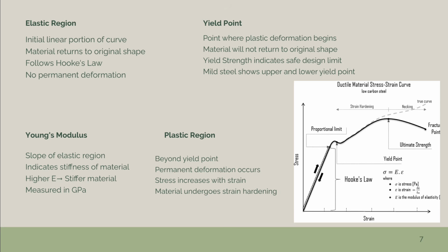The next stage is the strain hardening region. This region starts as the stress goes beyond the yield point, reaching a maximum at the ultimate strength point. This is the maximum stress that can be sustained and it is called ultimate tensile strength, UTS. The stress mainly increases as the material elongates, except for some materials such as steel, where there is a nearly flat region at the beginning.